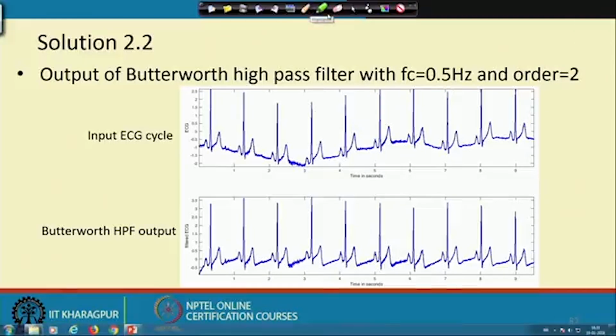That means, previous one we had the cutoff frequency 5 hertz. Now, we have gone to a new value, 0.5. We see it has improved the signal output quality. The distortion is less. What we can conclude is that in the previous case we were actually losing a good part of the signal energy also, which caused that distortion. Now, the signal looks more like the output signal.